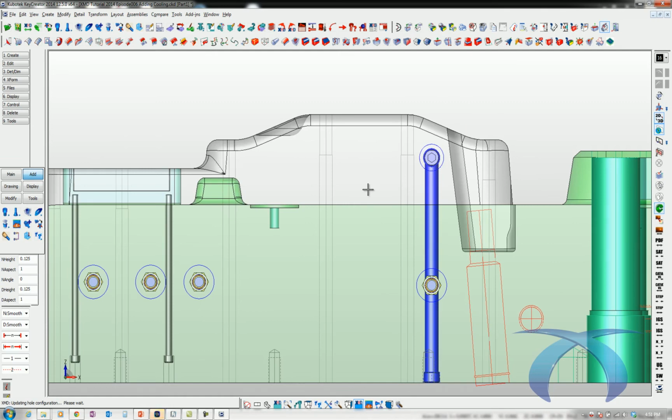Okay, so from here, what I'm going to do is I'm going to copy this water line to here, this whole circuit to here, and then I'm going to mirror copy this circuit over. So it's kind of symmetrical within this shape here. So I'm going to go ahead and do that. So I'm going to use the copy commands. Once again, these are the copy commands that we used in the previous tutorials.